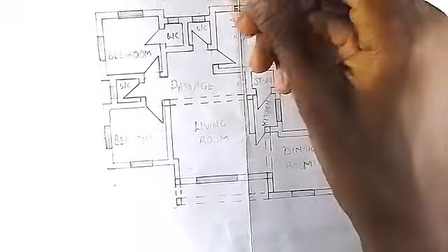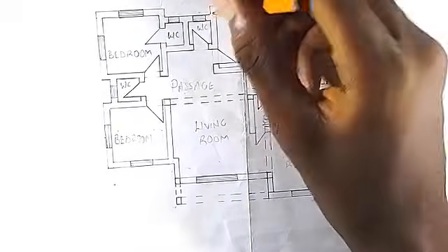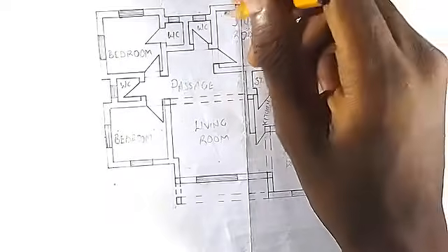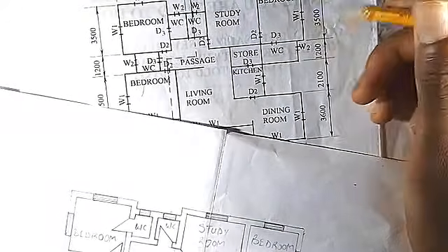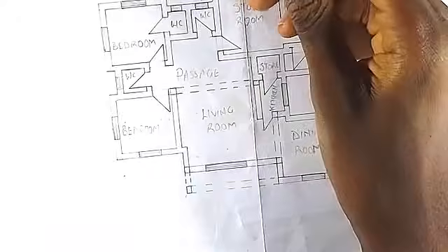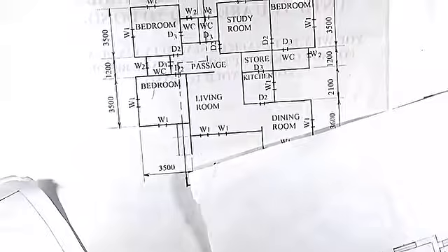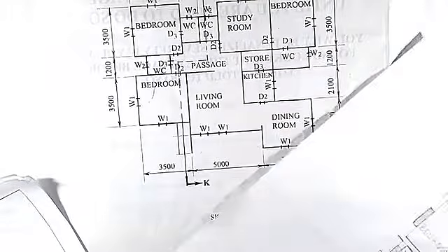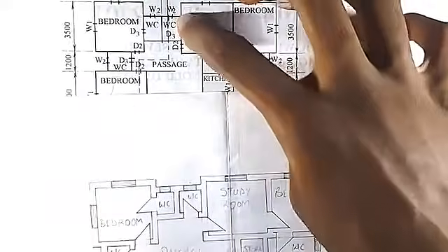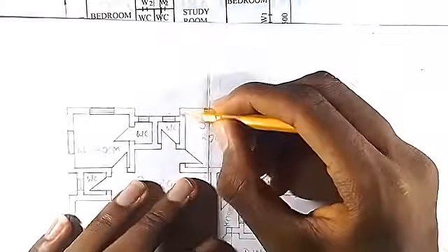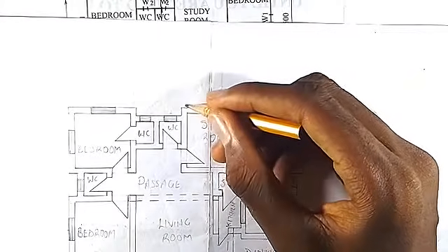Then when we section it, what we'll now do is we'll take the distance from here to here. So we'll just be drawing our walls, we'll be drawing the lines. From here to here, we're having 3.5 as the distance. But in our work, we're not going to use that distance. We'll use what we have here. Using a scale of 1:50, we're having our wall here. The first wall is here, and using this floor plan, we use 0.4 centimeter, which is giving us 400 millimeter.